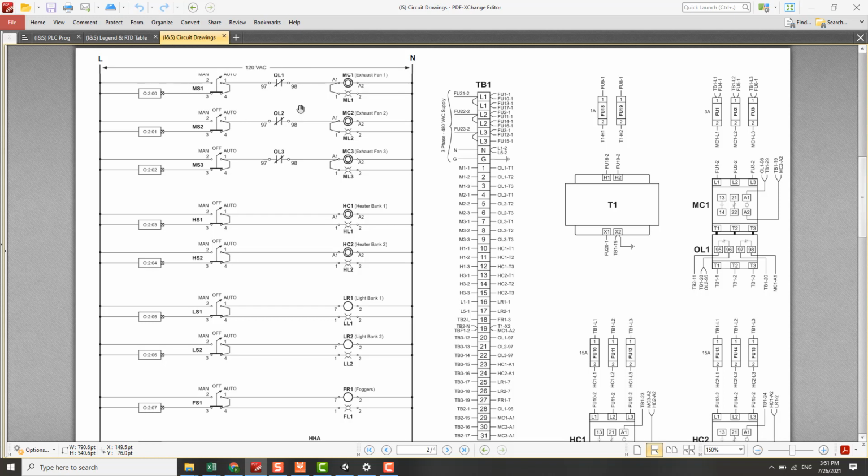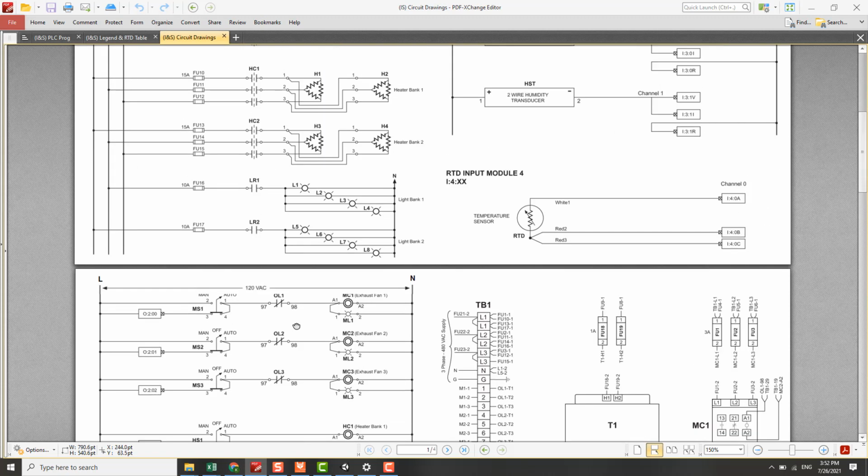It can be from the PLC output circuit itself, of course. It also can be due to the PLC CPU itself, meaning the PLC logic programming may be running the wrong program, the wrong program was downloaded, or the program is faulty. Actually, this kind of issue is extremely rare, if ever, so we can temporarily ignore this kind of problem. So the problem mostly can be from the PLC output circuit.